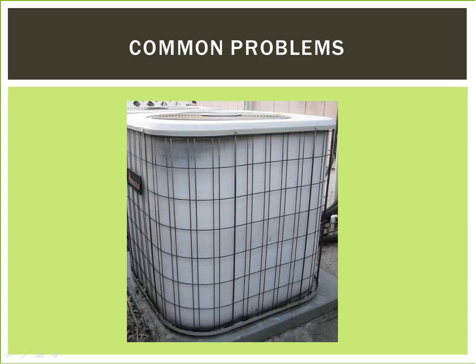Low refrigerant is another problem. If the system is experiencing moderate to severely low refrigerant, this will be evident in system pressures. In less extreme cases, a metering device or scale can be used to determine if system pressures are low. Low refrigerant can also be accompanied by irregular cycling of the compressor and fans. Another thing to consider with low refrigerant is the presence of leaks, so leak detection should be done as well.